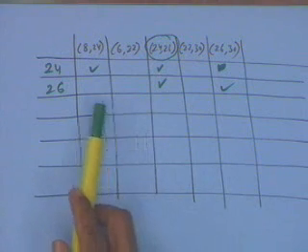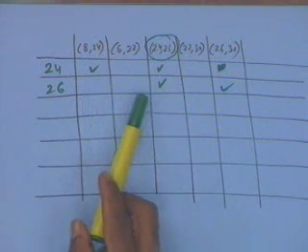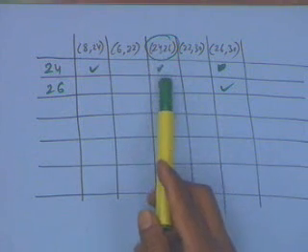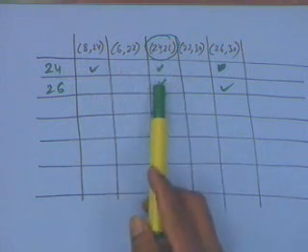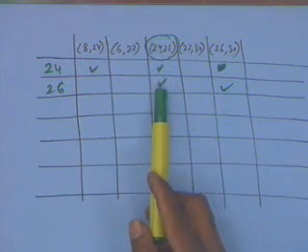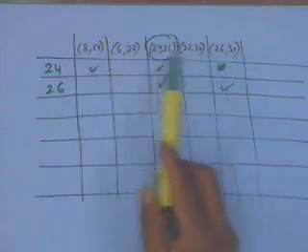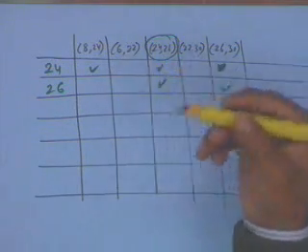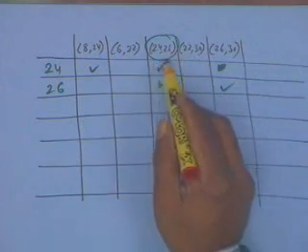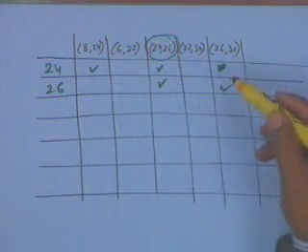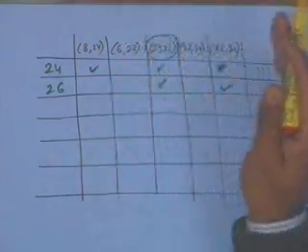So now if you look at this, the problem is quite simplified. Of course, in this case visually we can see that it is cheaper to use this particular implicant 24-26 rather than otherwise I have to take both of them. So in this case I can just choose this. Of course, in a very complex situation, this choice may not be so obvious. There could be, you would have to do some minimization to find out which of the subsets have to be